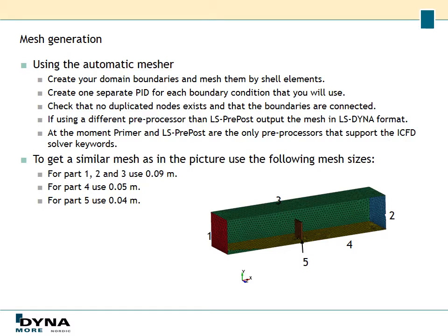After you have done that, check that you don't have any duplicated nodes and that all the boundaries are connected. And if you're using a different preprocessor than LS-PrePost, output the mesh in an LS-DYNA format, since at the moment only Primer and LS-PrePost support the eCFD keywords.